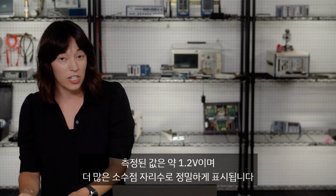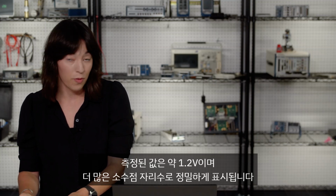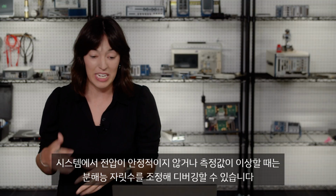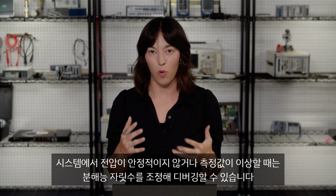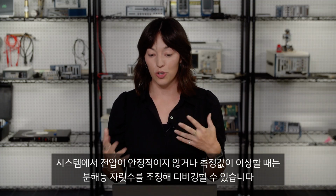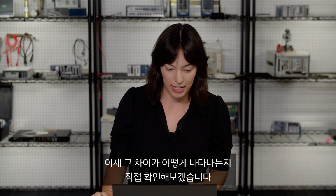Those digits give us a couple more digits off of the decimal point for more accuracy. But if I wanted to debug something in my system that doesn't have quite as stable of a voltage, or I'm seeing some measurements that don't quite make sense, that's when you might change the digits of resolution to do some debugging. So let's take a look at what that would look like.